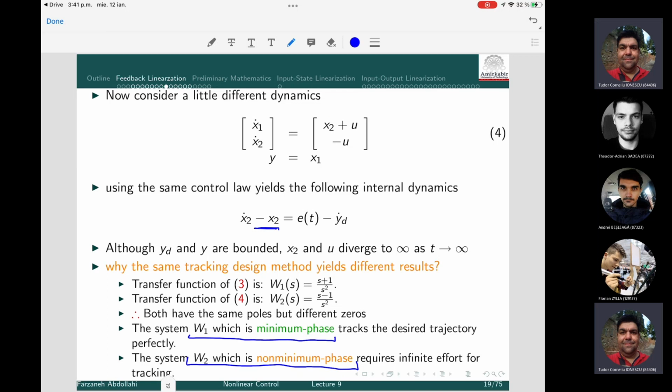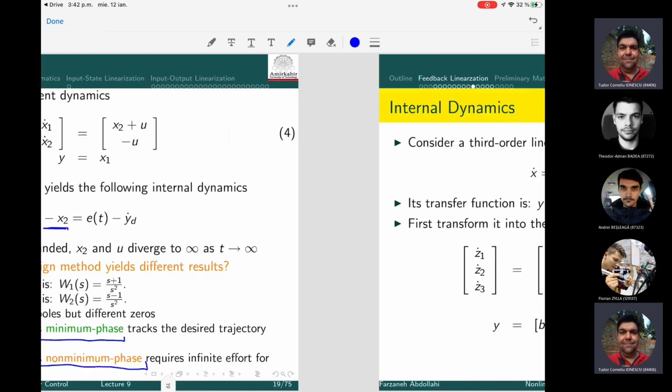If you remember the loop shaping you studied in the second year, there was a huge problem with non-minimum phase systems. The control design was far more complicated, and stabilization is an issue. Just take the simple system (s minus 1) over (s plus 1) and try to stabilize it with a PID, and see the problems because of the s minus 1 zero. So non-minimum phase systems are kind of a big problem.